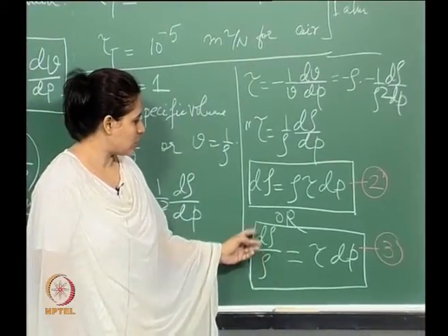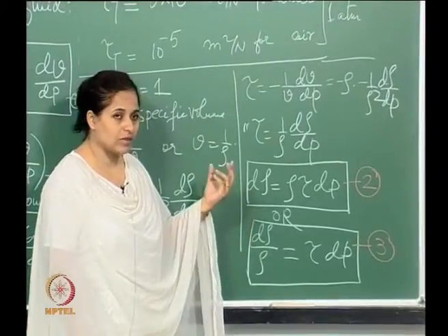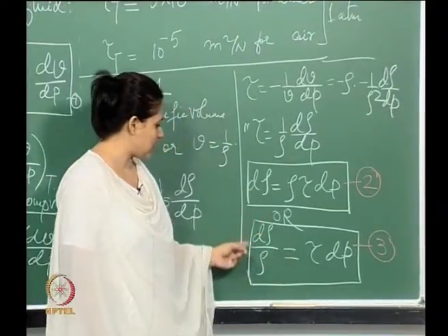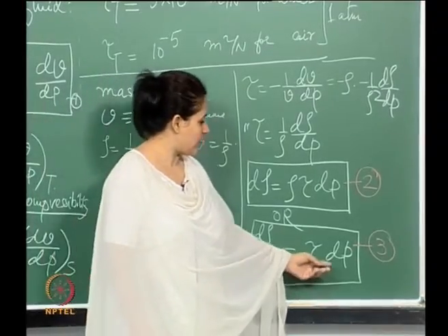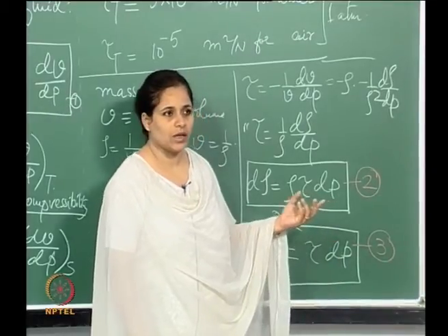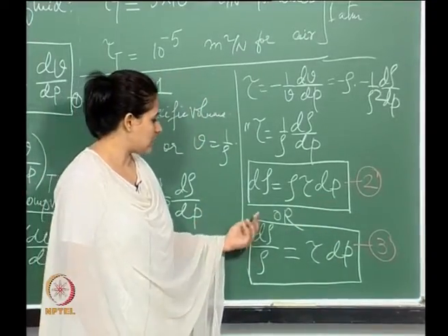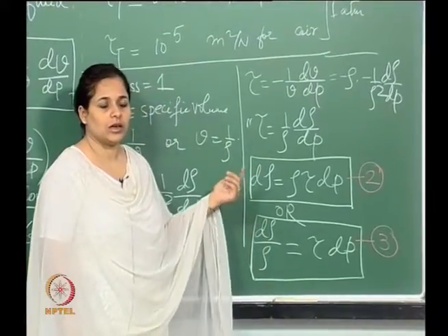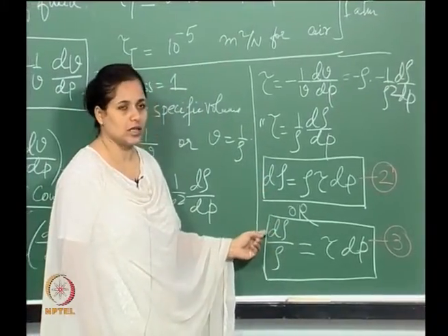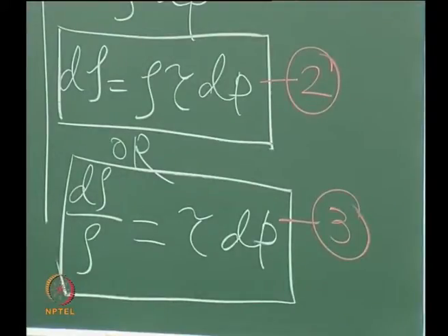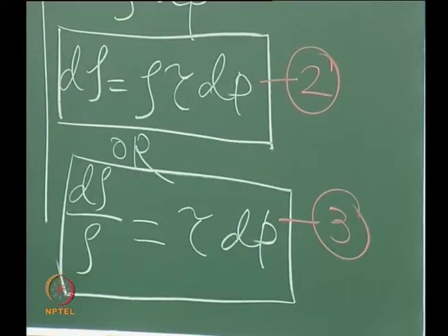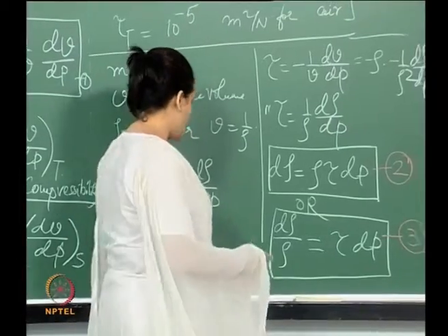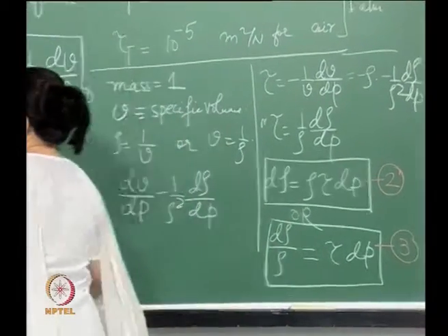So, therefore, you can see here this is the fractional change in density, right. So, for a given pressure change, for air for example, there is going to be a much larger density change compared to say water, essentially because this compressibility factor here is much larger for air than for liquid. Having said that, now let us go back to your previous problem.